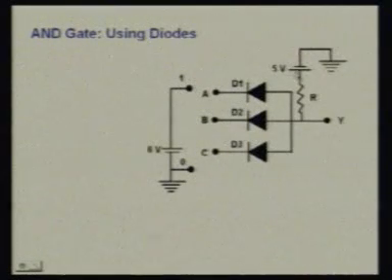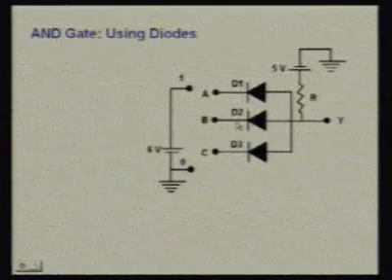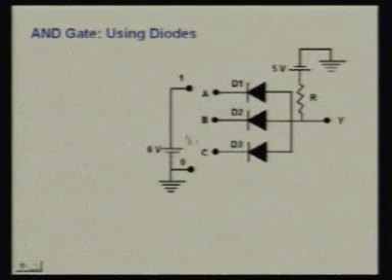Sometimes due to some electronic fluctuation, because we need only 0.2 volt if it is made of germanium to transfer the diode into the saturation state, this is very low, and due to any electronic fluctuation, it can go beyond 0.2 volt and the diode may go into saturation. So to keep our electronic device, the AND gate, on the safer side, we take 6 volt, which is a higher voltage than 5 volt.